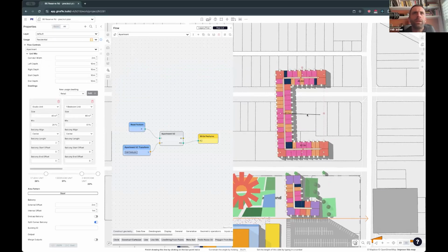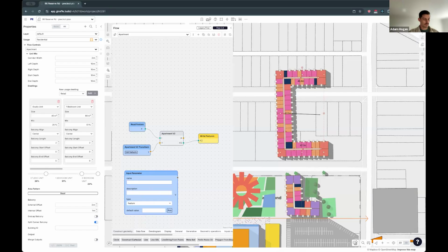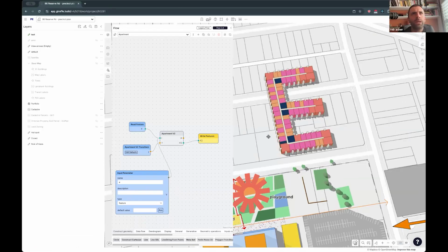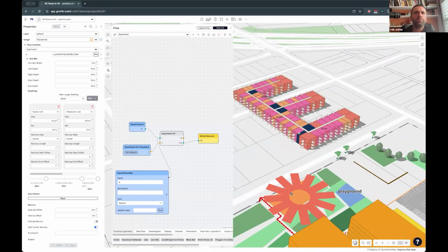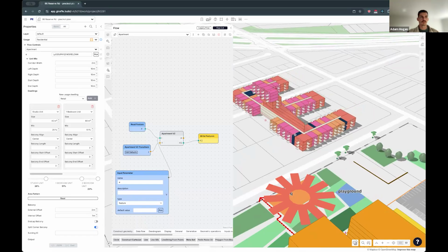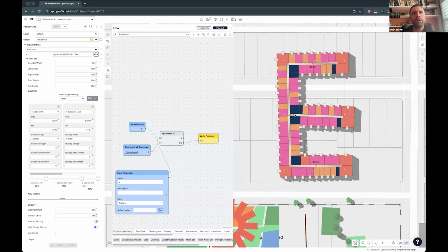So what I'm going to do is get that line and feed it to this algorithm. When I come to the flow editor, I add an input parameter, and I want another feature. A line is a feature. Call it E, and you can see it goes to the flow inputs there. Now I'll pick that line and do this. There you go. Now that E has healed across. It'll try and heal as best it can across these nodes, and you can see it does get a little bit off. So just make sure that you bring the line close.